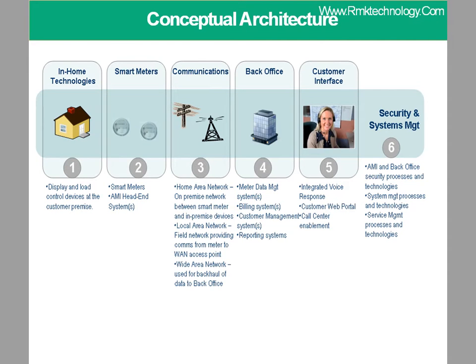This slide depicts main components involved in smart metering solutions. Smart metering infrastructure comprises smart meters and communication of data from smart meters to head-end systems. From this head-end system data goes to the meter data management system and subsequently to the smart meter app. Other considerations like security and customer are also very vital. There are control devices like air conditioner control etc. that can also be linked to the network. These are called in-home devices. Security is very important for preventing any alien meters or devices being introduced in the network to disrupt the system.